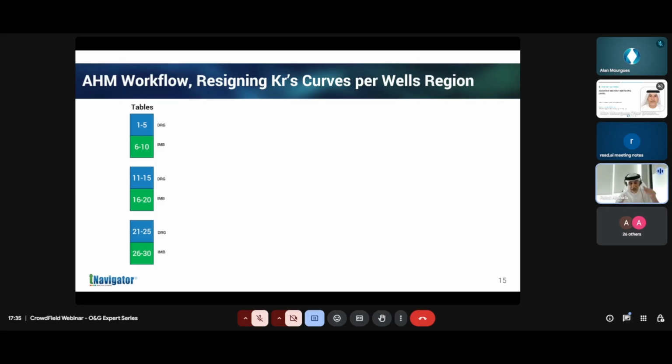Then I create another set, the third type, which is from editing those original ones, becoming 21 to 30. So in total I have 30 tables representing different sets of relative permeabilities, from high water mobility, intermediate, to low water mobility, or to gas, where I will let the assisted history match test those tables to see how they impact the history match.